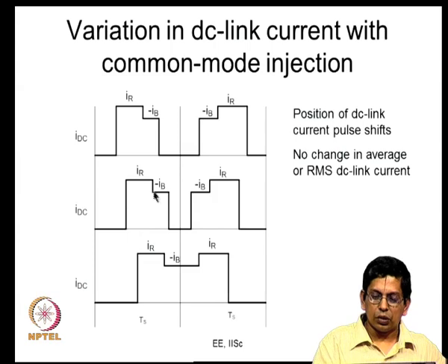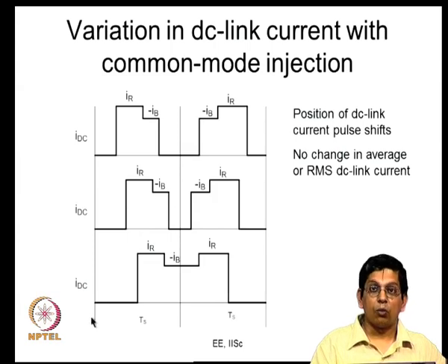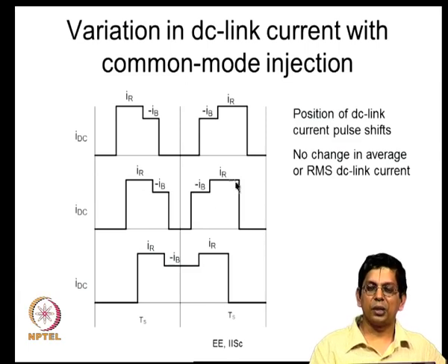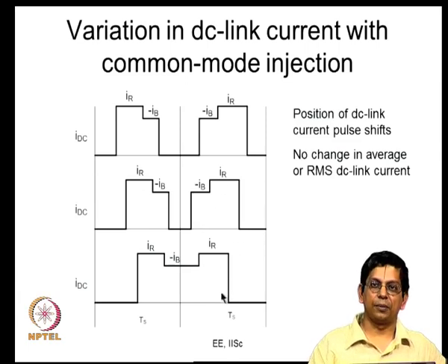So, I have shown that this is shifting to the right. What happens as an extreme case if T7 becomes 0? If T7 becomes 0, then this pulse and that pulse come and combine with one another, and you get a pulse of this nature, and within every 2 subcycles you will see one such large pulse here, whereas here you will see one pulse in every subcycle.